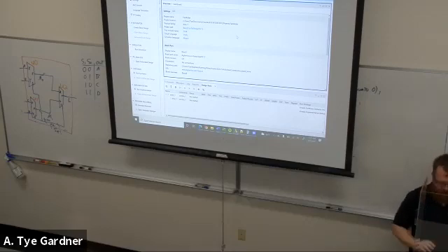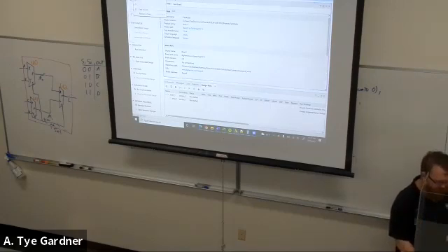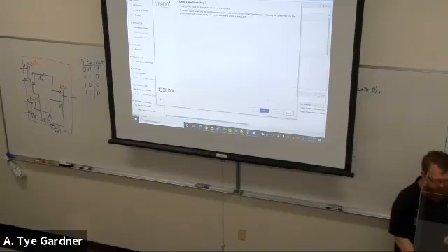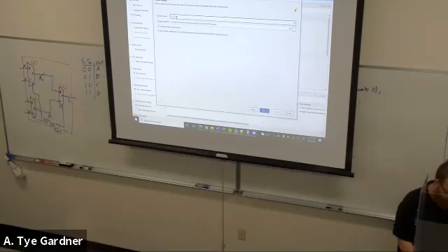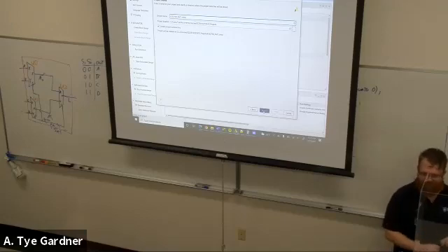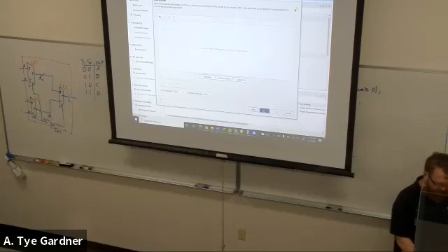Okay, when you meet Vivado, it's going to pop up with something like this. You're going to need to create a new project. So we'll go File, Project, New. It's going to create this little wizard for you that you can walk through. Give it a name. I'm going to call it something descriptive, ECE2700 FA21 intro. There we go. That's probably a good name, right? Now I know what it is, so that I can go delete it later. All right.